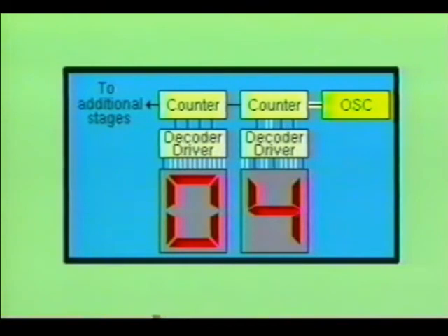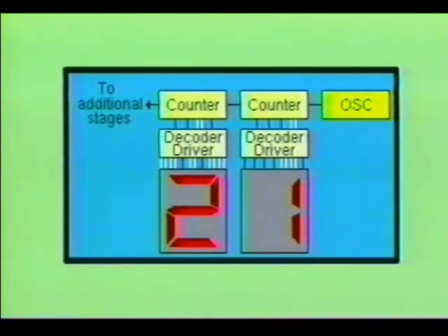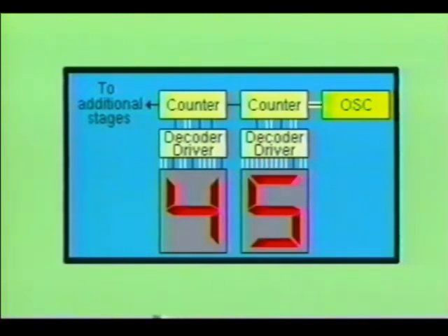This pulse activates the second counter circuit and causes it to produce BCD-coded outputs into its decoder driver circuit. The decoder driver IC causes the 7-segment display to show the divided down pulses in a numerical form. By simply adding more counter decoder driver 7-segment display devices, this circuit can be made to count to any desired length.